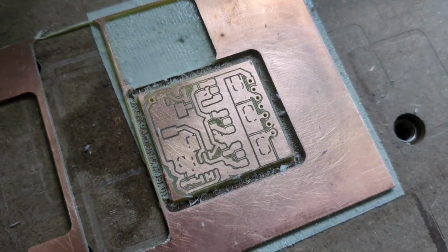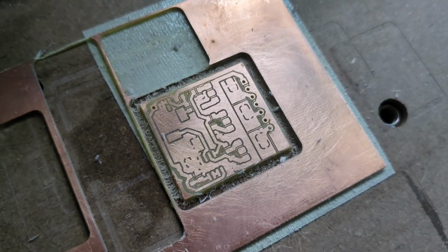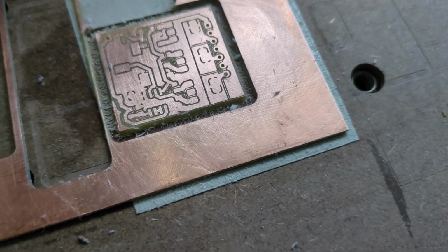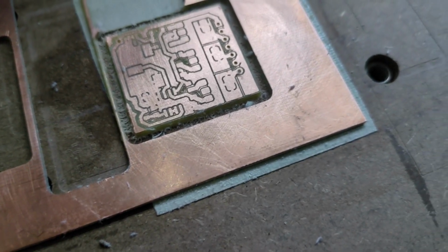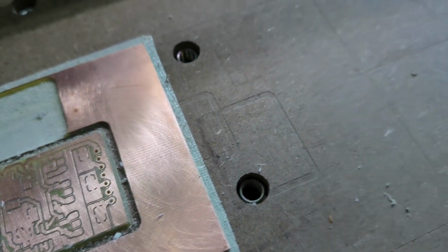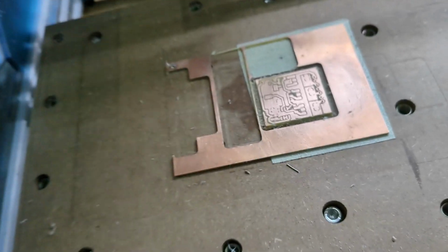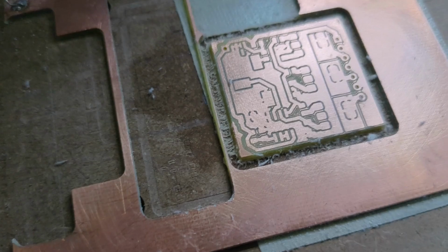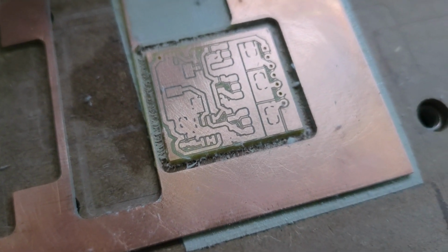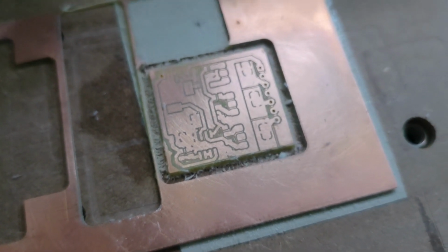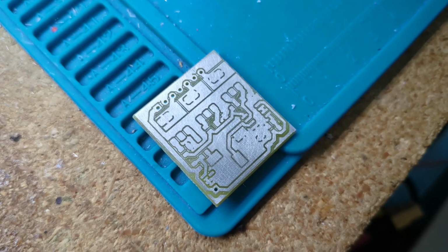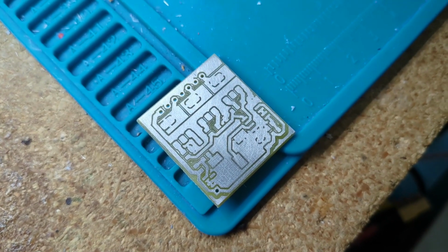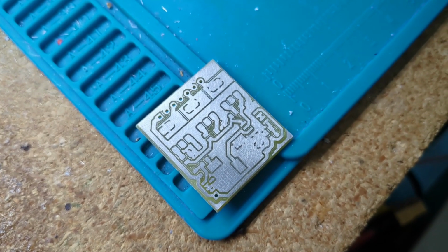So there it is, all cut out, and it looks good. So the next step is I'm going to add some what's called tinning compound. I don't know if I can see it where I'm standing. Yeah, right here. This liquid tin stuff, it's optional, but it helps to keep the copper from oxidizing. And then I'm going to cut out a stencil to make the soldering easier. So that comes next. There it is, all tinned up and ready for the next step, which is to apply solder via the solder stencil I'm about to cut out.